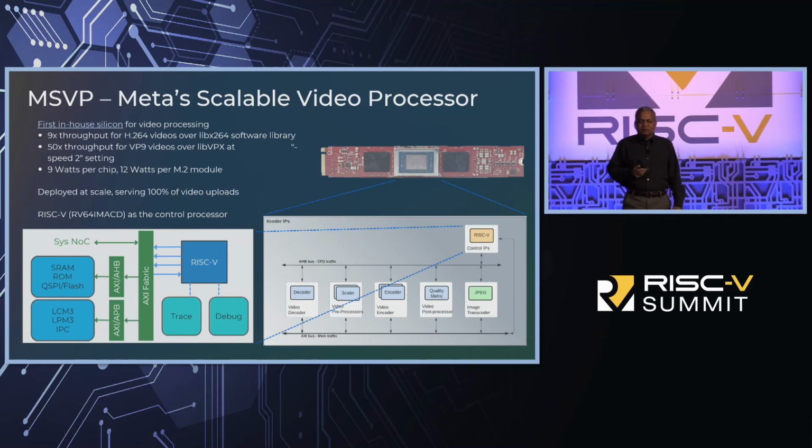So if you look at the purpose of this control processor, this RISC processor essentially does a very complex function. It utilizes the full capacity of that 4K 60 video capability and splits it into multiple sessions of smaller resolutions at frame boundary. So it's all different sessions. It also realizes sequence level, picture level at that level, and then the accelerator essentially takes care of the slice level, right?